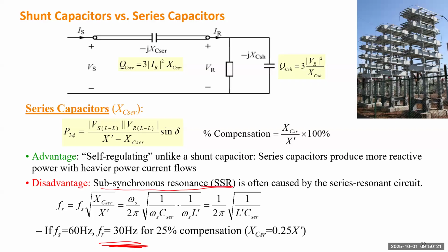This becomes an increasing challenge to operators when you integrate a lot of renewables, and sometimes you need to add compensation to a long transmission line. For instance, if you have wind farms far away from your city, but you want to deliver electricity over a long distance, and you want to make the line electrically shorter by adding series capacitance to cancel some line impedance, you will introduce some subsynchronous resonance.